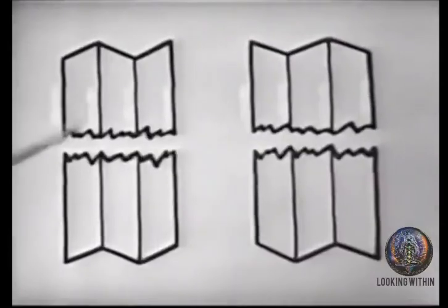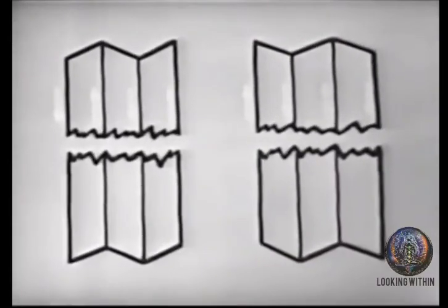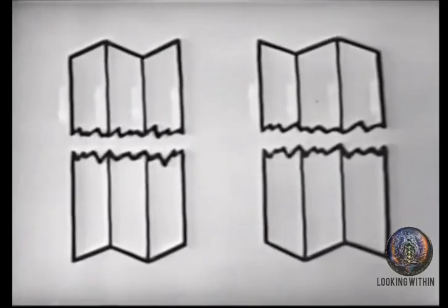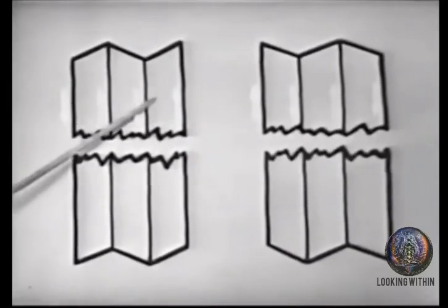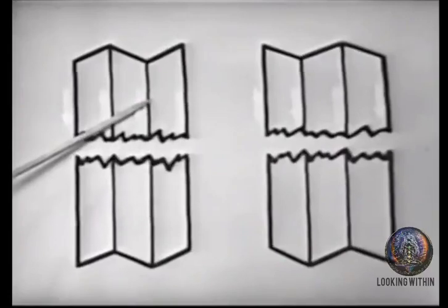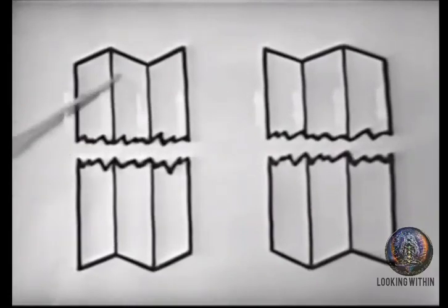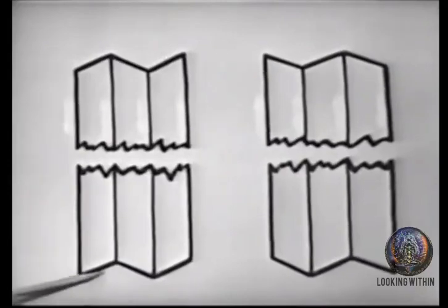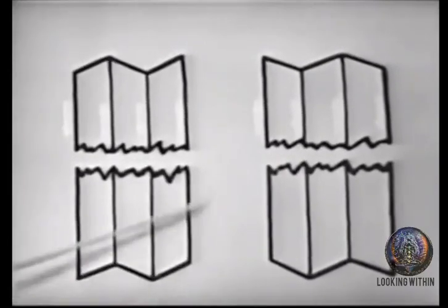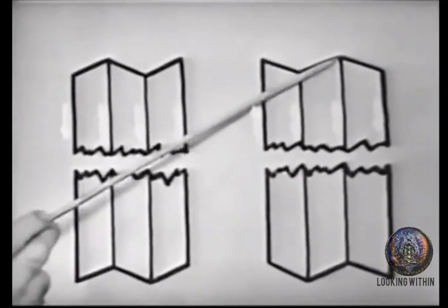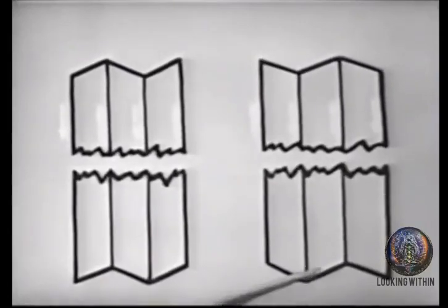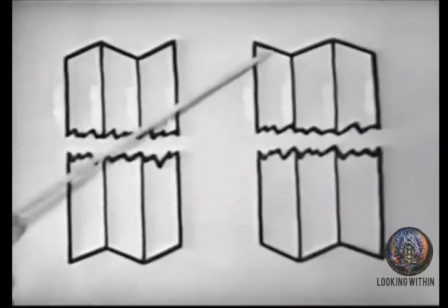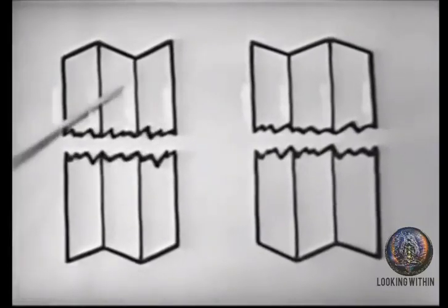Now here we're representing the crystal when it's made to oscillate in the third overtone. Now let's notice that the crystal breaks up into 3 layers when it's oscillating at the third overtone. Now this is representing the deformed layers to produce one alternation. Here, the deformed layers for the other alternation. And let's notice that the deformities are opposite for each alternation.